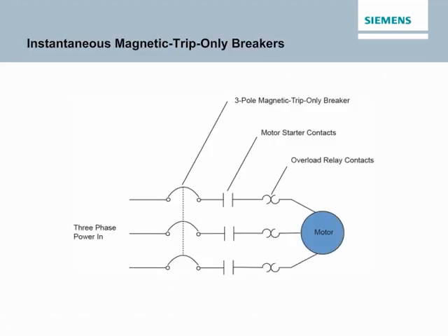A thermomagnetic circuit breaker is so called because it has a trip unit that senses heat to detect an overload and senses a magnetic field generated by current to detect a short circuit. As described earlier in the course, this type of circuit breaker trips immediately when a short circuit occurs, but delays an appropriate amount of time before tripping in the event of an overload.